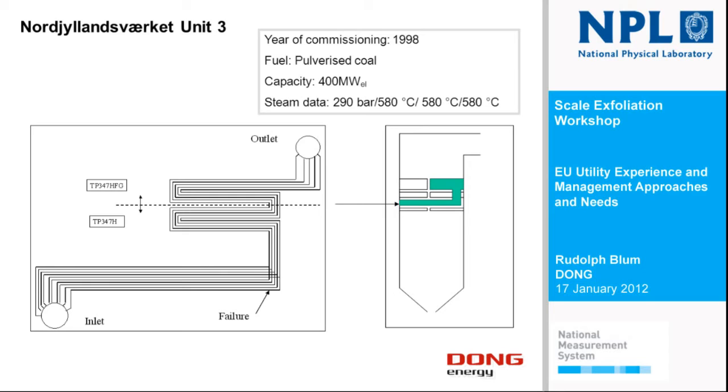And our main concern in those days was actually whether we would have some thermal fatigue problems or damages in the main outlet and so on. We made careful analysis and said, well, this outlet might be able to stand for such a treatment 5 times. So okay, 1 time is enough. We will never do it again. So just bring the boiler into operation. But then very soon after we began operation with this boiler, we had a failure. And we had some more failures.